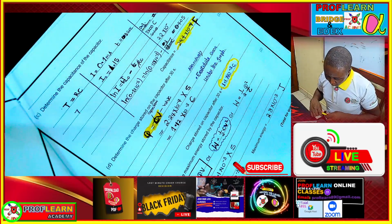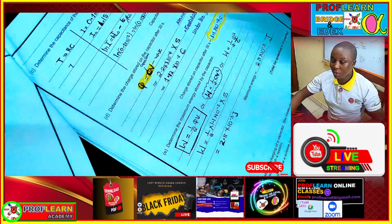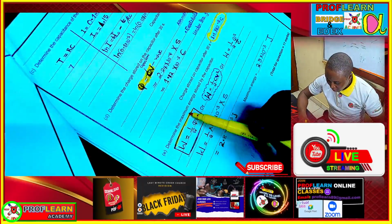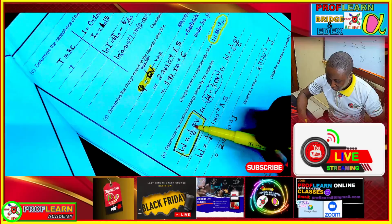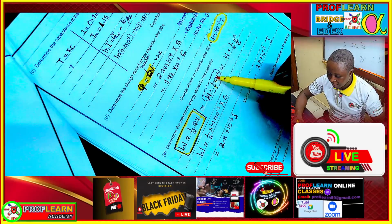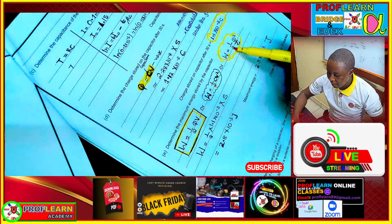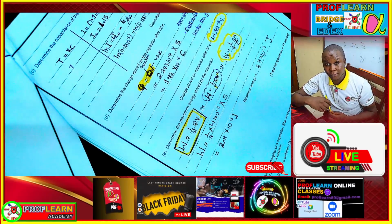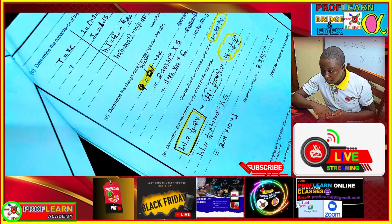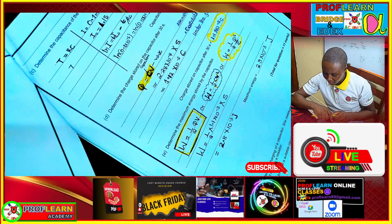If you are asked to determine the maximum energy stored, you need to remember that energy stored is the same as the work done. Energy stored can be given by the formula a half QV, charge times voltage. It can be given as a half capacitance times voltage squared, or you can also work it using the formula a half Q squared over C. So those are the possible formulas that you have at your disposal in order to work out the maximum energy stored.